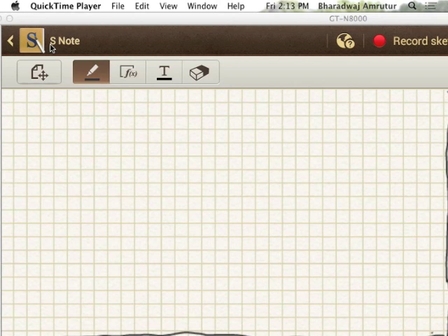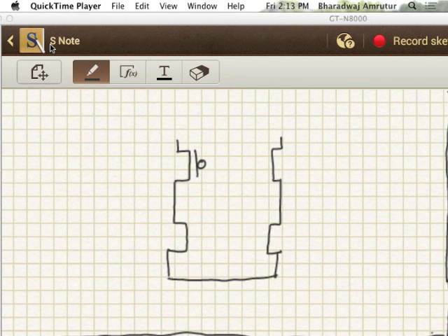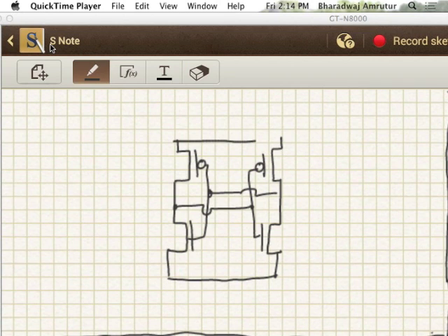Okay, so let's look at the writes and see how a write happens and why a write can fail and what you should do to ensure that the write doesn't fail. Okay, so we'll go back to our memory cell, which is the standard 6 transistor cell. So we have basically two back-to-back inverters. Then we said this is V cell. Okay, and then these storage nodes Q and Q bar can be accessed through these access transistors.